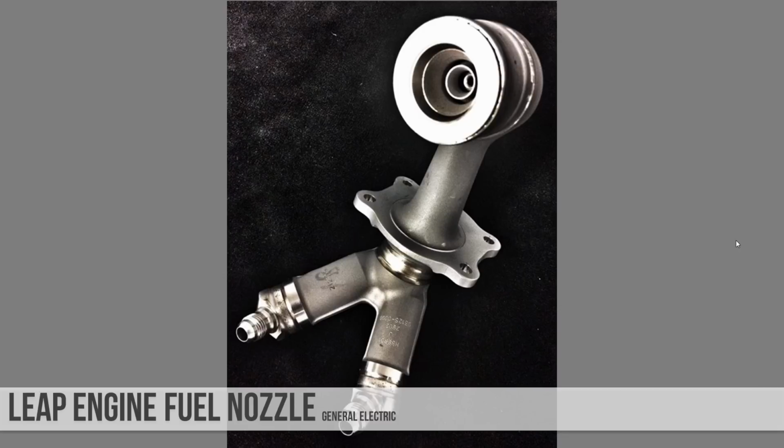The printed nozzles are actually 5 times more durable than the previous model. It also allows them to, again, use a simpler design. This isn't printed as a single part, but it's been consolidated from 25 different parts to 5 different parts that are then brazed and welded together. It also helps with weight and heat management.